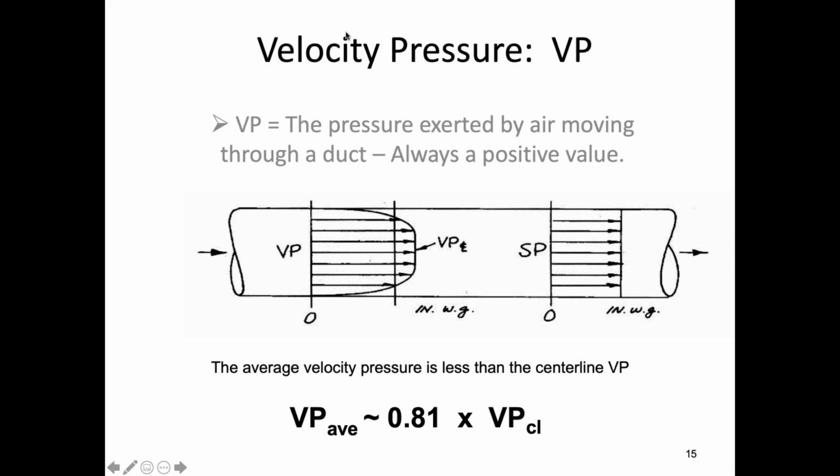If I put this into the ductwork and the air is flowing in here, right, it's blowing against this and it's going through this tube, coming out here, and I connect that to a manometer, am I measuring static pressure or velocity pressure? Velocity pressure. Yeah, that's a trick question.